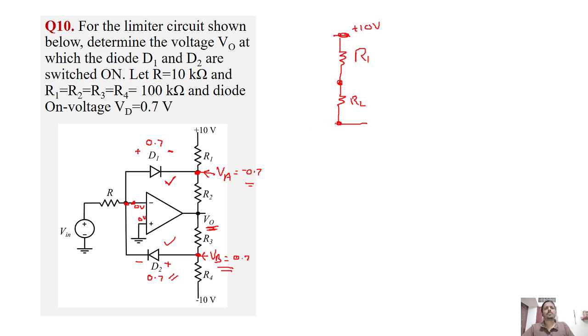Okay, so this is the output of op amp V0. We need to find the value of voltage VA here. How will we find it? We'll just apply the superposition theorem. While applying the superposition theorem, we'll find the value of VA due to each of the sources. So for example, if V0 is present, we'll assume this to be grounded.